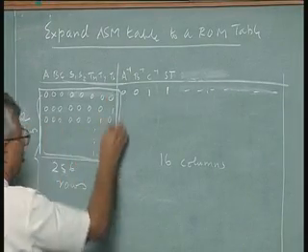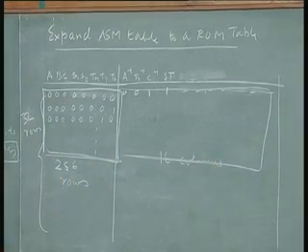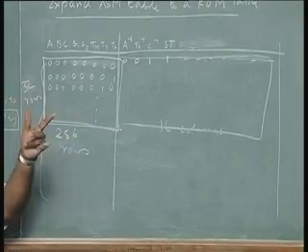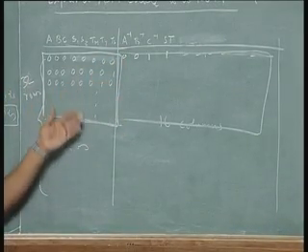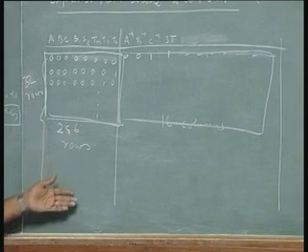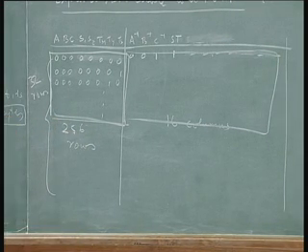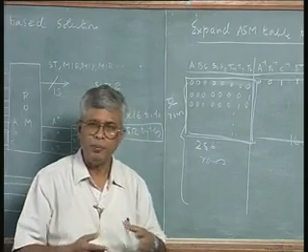All of them having the same output. This block will have same output. So, you have to store in 32 locations, first 32 locations of the RAM, the same word, 16-bit word. Like that you go to the second, and you have to exhaust all the 8 states. So, that is how you get the ROM table. So, all you need to do is to get an expanded ROM table and program the ROM for this application.